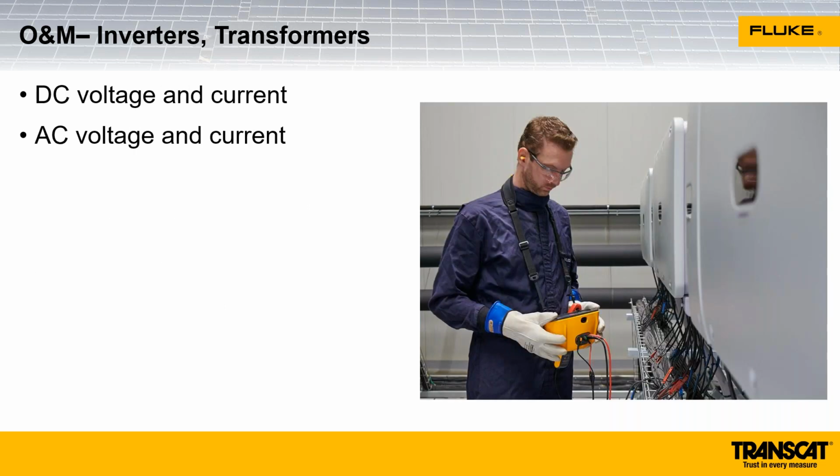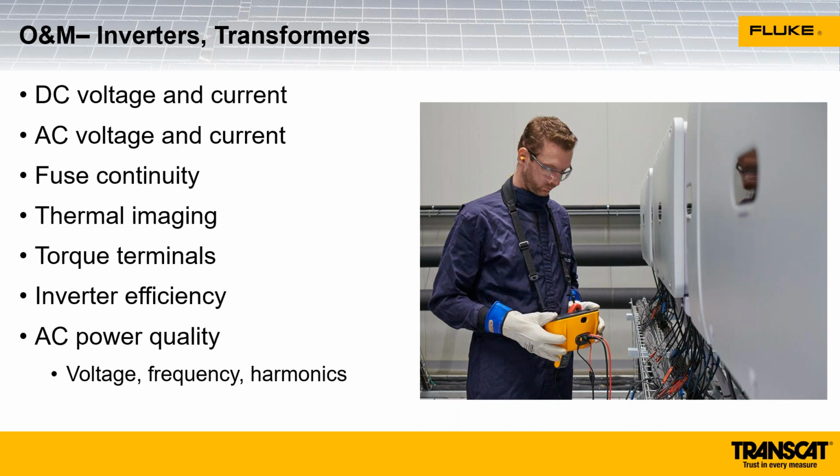Okay, when we get into inverters and transformers, they need operations and maintenance as well. We're going to measure DC voltage and current, AC voltage and current. We can check the continuity of fuses. We'll often do thermal imaging on inverters and transformers to ensure that they're working properly.